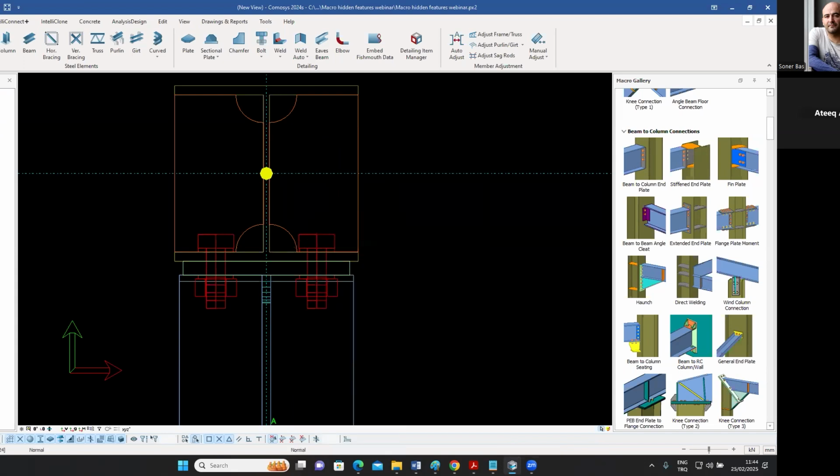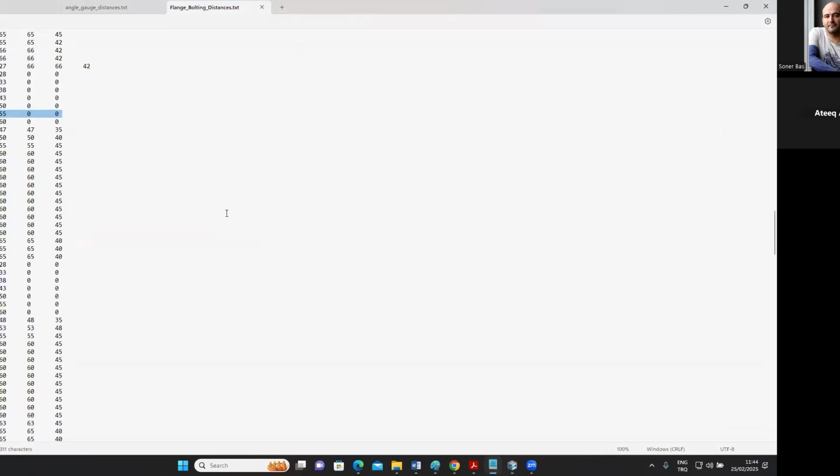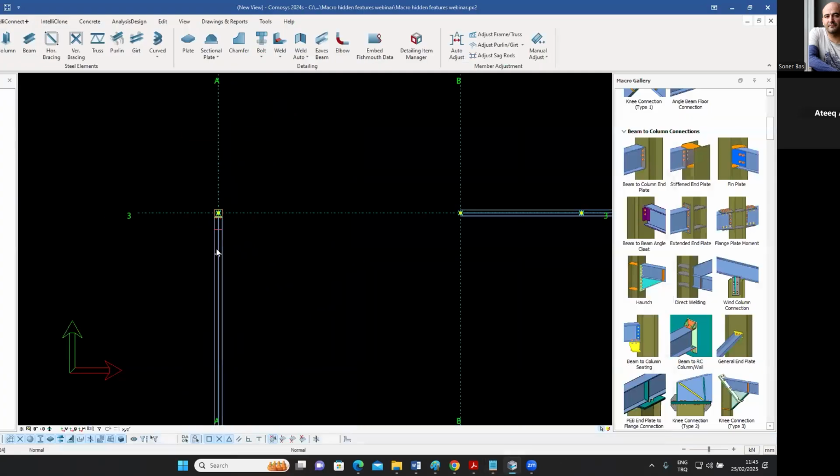This is very useful because what it's doing over here, it's saving me a lot of time. It's allowing me to do a one-click connect. Now there are other things which of course might be coming to your mind. What about the plate thicknesses and what about this and what about that? We'll talk about those as well at some point. But the idea is that the inter-bolt distances, the bolt gauge lengths, etc., are very time consuming to remember. And if you see over here, automatically it's using the recommended bolt size, the recommended gauge distance.